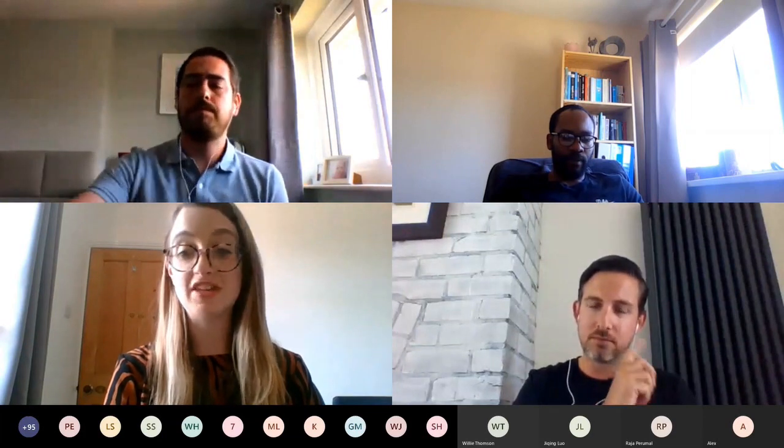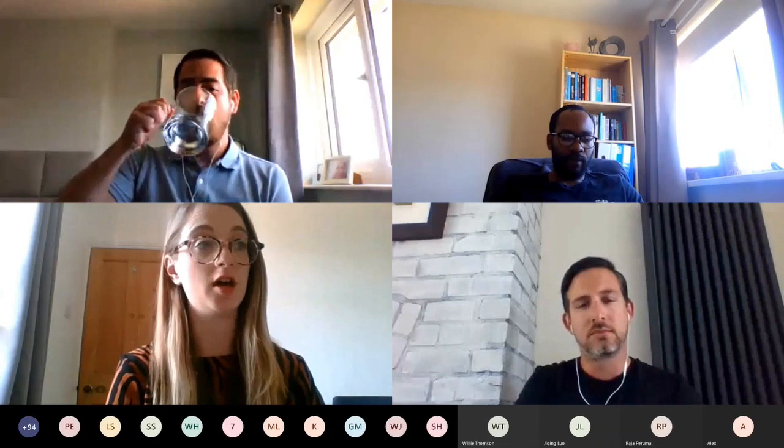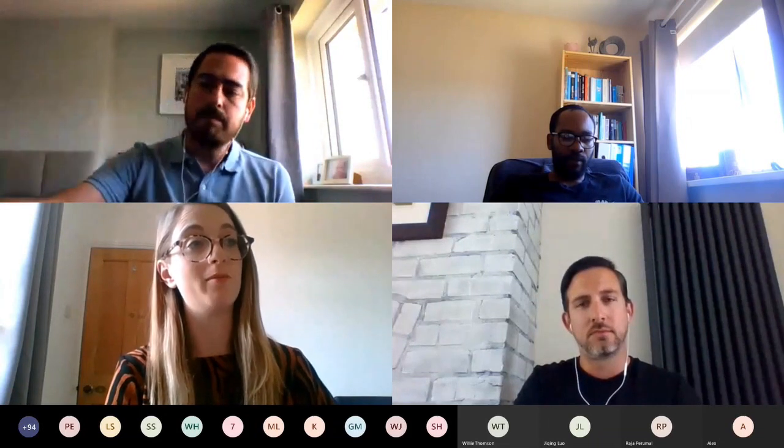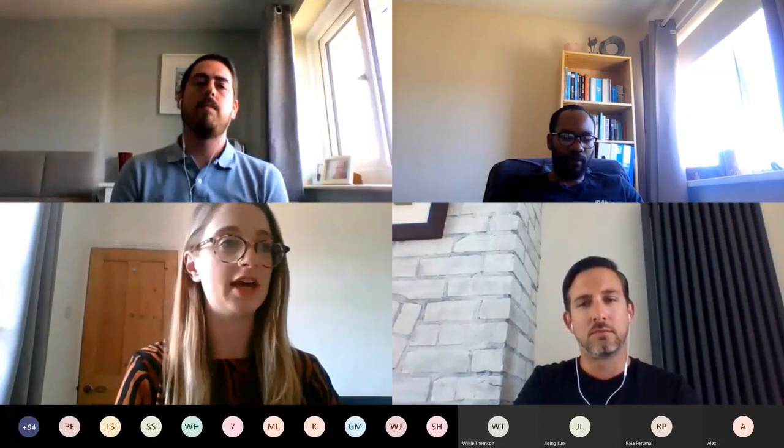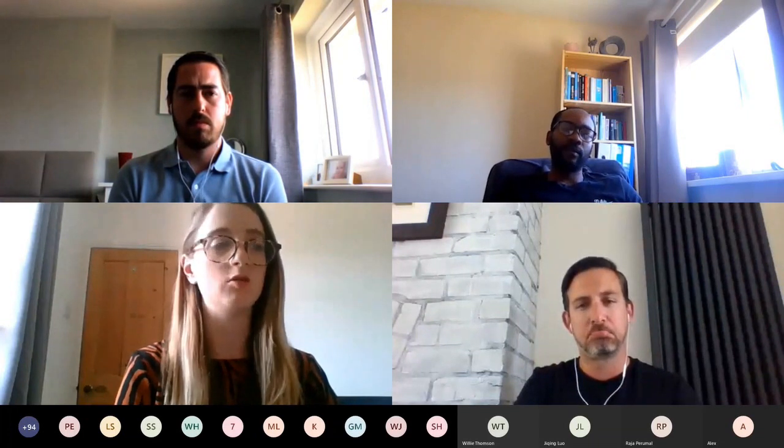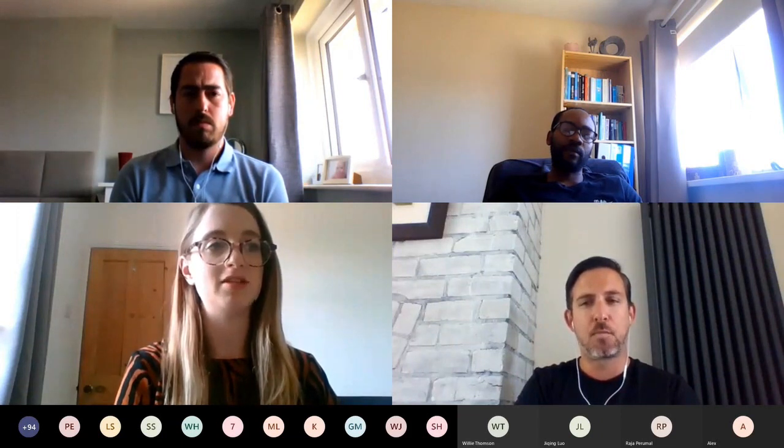I mean, we did have a specific question that was submitted through the forum. That was from Mukund from Petrofac, who I know is on the session today. With reference to the latest IEC 60079-14 2013 clause 10.6.2, he was asking whether, for a typical oil and gas project installation, a barrier type gland shall be applied for any EXD equipment if the connected cable length is less than 3 meters. This is irrespective of the internal volume of the enclosure and the gas group.